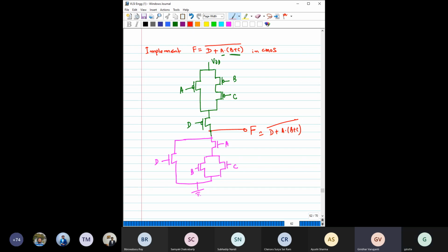So we can also draw this like at first we will draw B plus C whole bar, then put the output in another CMOS inverter, then from the output we will get B plus C. Then we will AND that output with A. Right, but then it will be multi-stage, na? Yes. Multi-stage means you can make multi-stage, but if you make a single gate using multi-stages, then what will happen? You have this stage delay, right? Yes. It has to be calculated, na? Right. Okay.